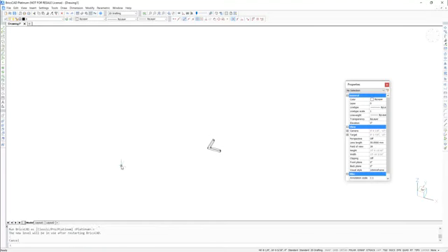Okay, let me go back to Run As Level. So I'll change BricsCAD back to Platinum. Now, if you want to experiment with some of the BIM or sheet metal modules, again, you can use Run As Level for that. So remember that BricsCAD has to be set to Platinum for sheet metal or BIM to work.